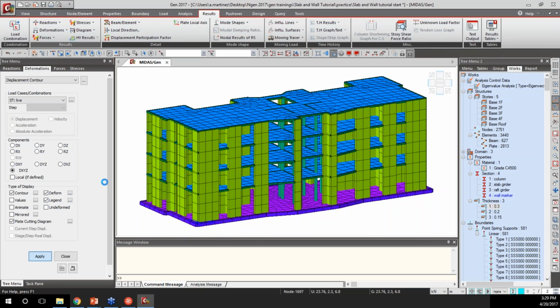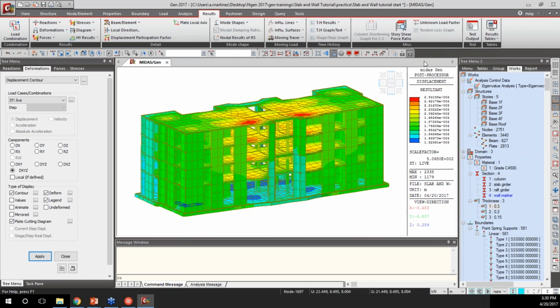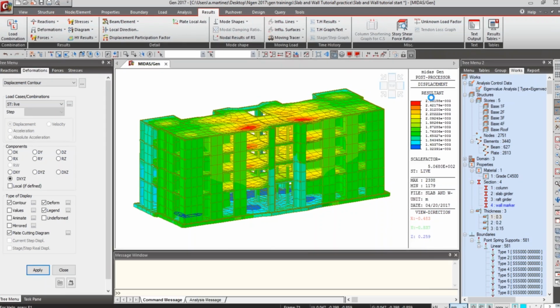The default is to give you the results in exponential format, but we can control that. So you see here, we see it as 2.5 to the -3 meters. So I can change these units to millimeters, and then just update it, because I just wanted to see it in decimal, not in exponential format.